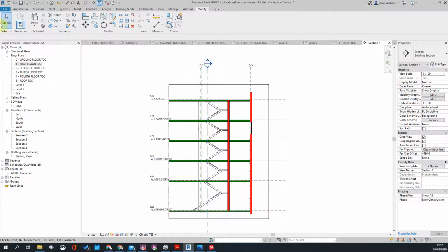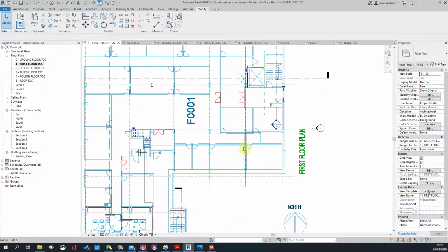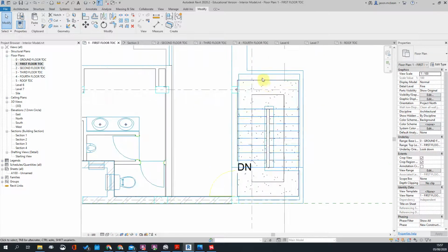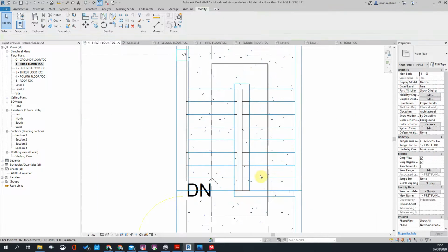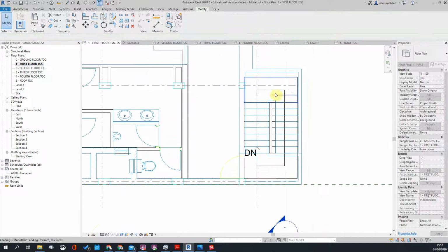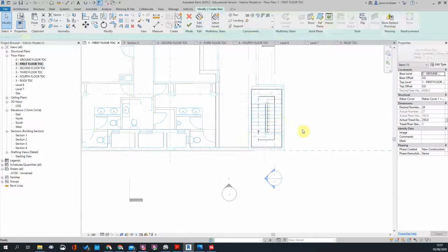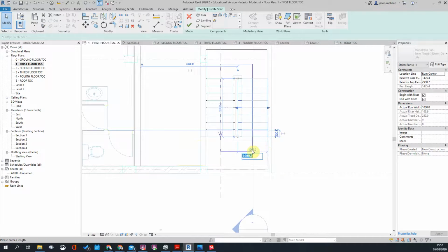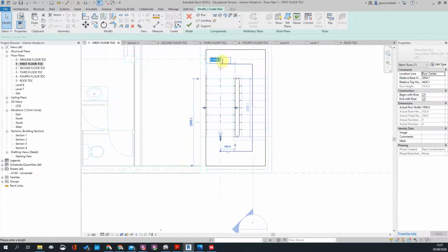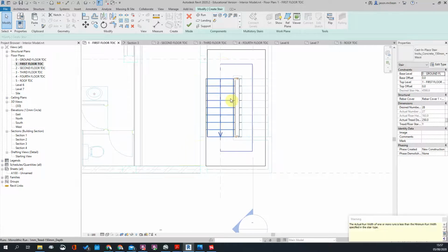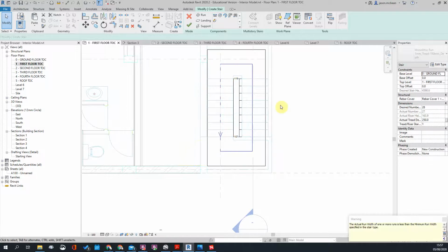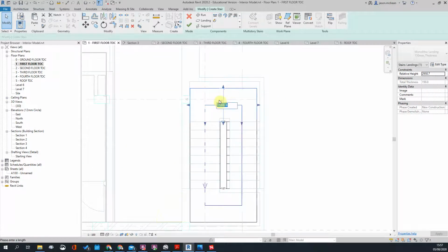We'll make the shaft work a bit better. The staircase needs to be fixed as well. So you just see how wide these staircases are. 900. Okay, so get a staircase 900. One beneath, that's also 900. Your landings will be 900.